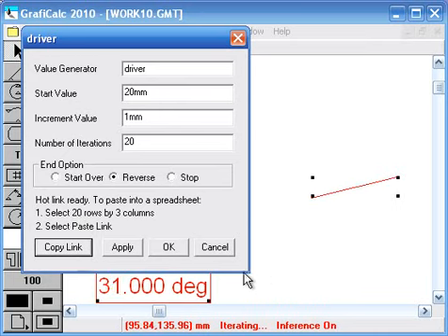I've selected 3 entities, so start Excel and paste it, use a paste link, and then the Excel sheet will be dynamically updated as the value generator is going through its iterations. So this is a very good way to get snapshots of the behavior of your model using a dynamic update of the Excel spreadsheet. This is different than the transient data collection feature that we will be talking about a little later.